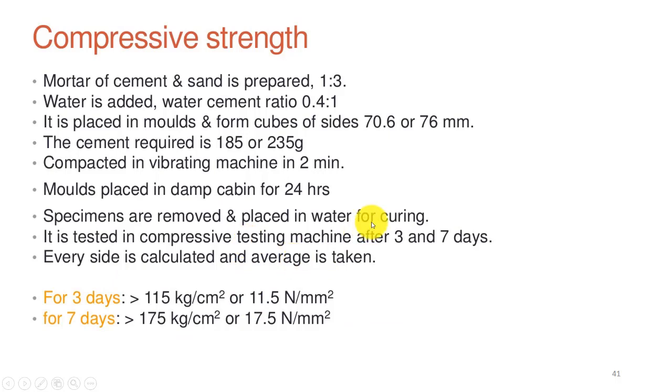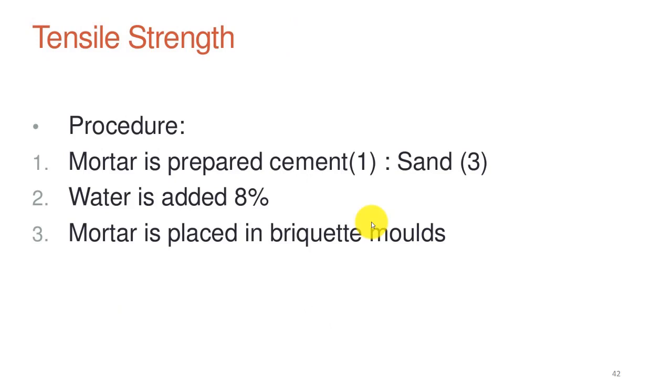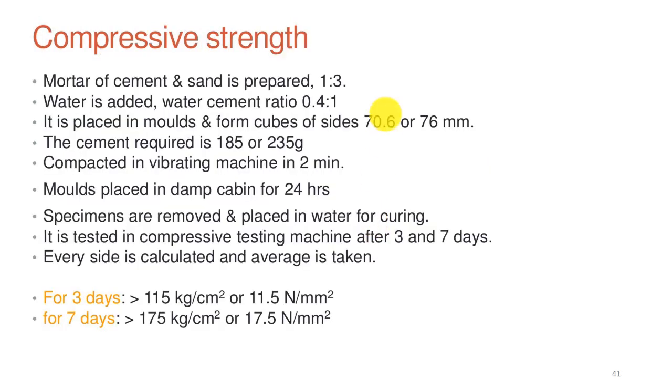So compressive strength of a cement is very important. It's a prime property by which we can identify the cement, whether it's an ordinary Portland cement, a rapid hardening cement, or a low heat cement. Its compressive strength is a very prime structural property, a prime mechanical property which adds to the structural value of a concrete. So you prepare the desired mix with the desired constituents.